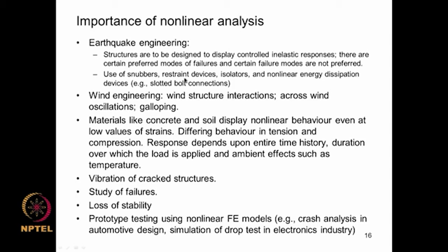To cope with thermal loads, the structure needs to be flexible, but that very flexibility brings the natural frequency of the system into the range of earthquake excitation frequencies. So, supports like snubbers, in the event of an earthquake, lock the structure and reduce the spans of the piping and increase the natural frequency, so that it attracts lesser seismic loads.